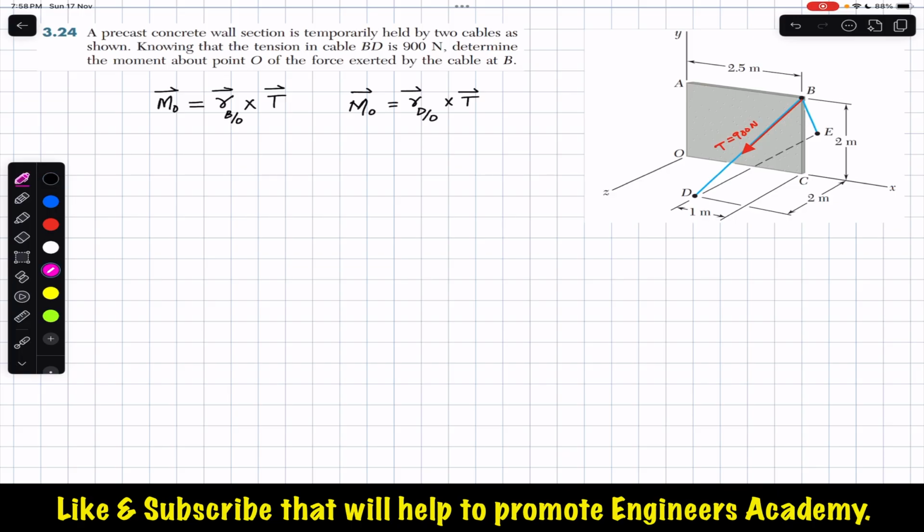So this will be the position vector of B relative to O if we draw a vector from O to B. The pink one is R of B relative to O, or this will be R of D relative to O. So this one is R of D relative to O. Both must give us the same moment. So this could be any position vector starting from the point about which we want to find the moment, and ending on a point on the line of action of the force for which we want to find the moment.